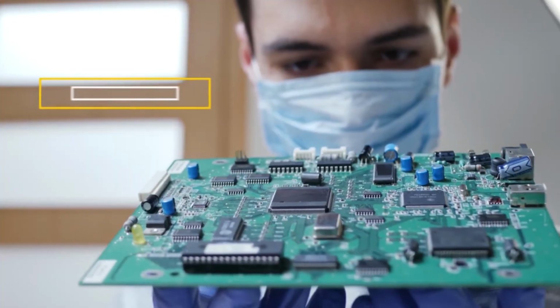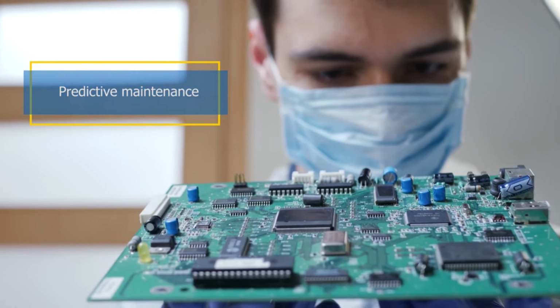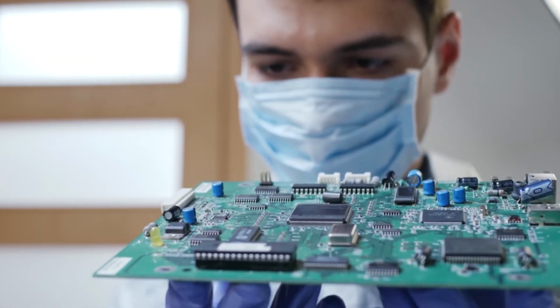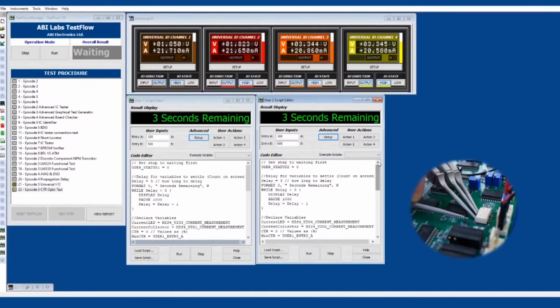We use these values, did a calculation to produce the CTR, the current transfer ratio, and then again we check this against the datasheet to make sure that our value lies within what the datasheet says. And again, this is another parametric test that we created with some of the instruments available with the MIS4.